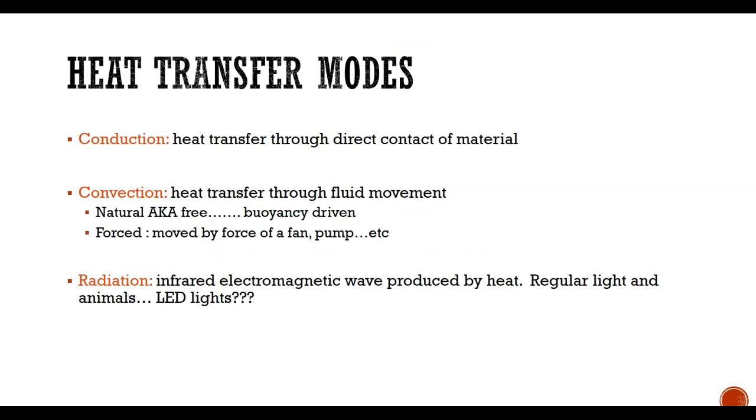So we burn the fuel inside the boiler, we heat the water or steam. How do we transfer that heat into the house? We did talk about this before, that heat transfers from one place to another using conduction, which is heat transfer through direct contact with material, or convection, which is heat transfer through fluid, either natural convection, which is the idea that hot air or hot liquid rises based on density and is buoyancy driven, or forced convection, where you have to use a fan or a pump to move the fluid faster from one area to another.